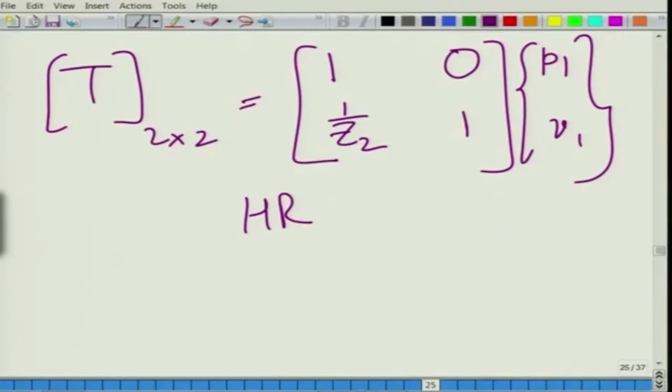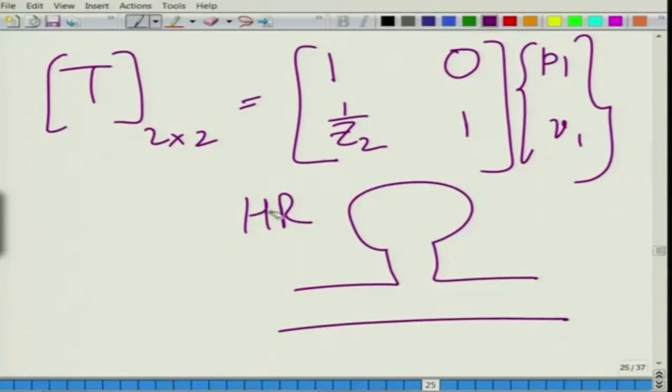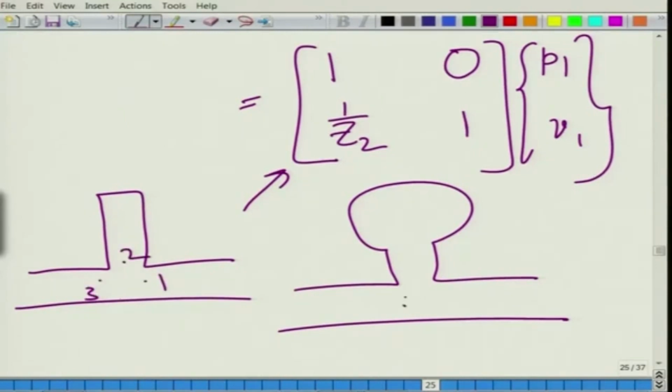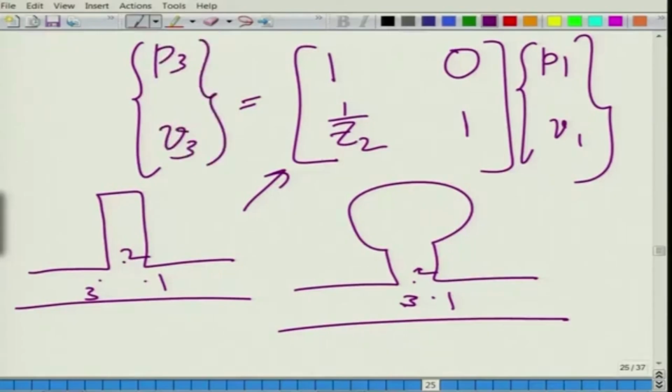and in principle this is exactly the same form for a quarter wave resonator which acts like a side branch. So, basically whether you have this system or you have a simple quarter wave resonator acting like a side branch, they are always represented by the shunt element. The circuit for that was shown in a slide back, and this is the transfer matrix relation. So, this represents 3, 2 and 1, P3 and V3.